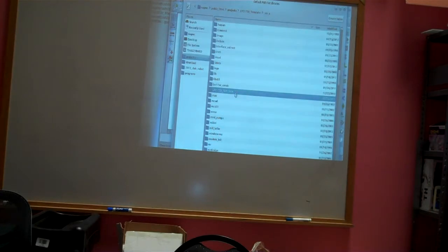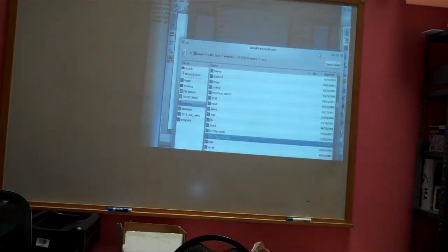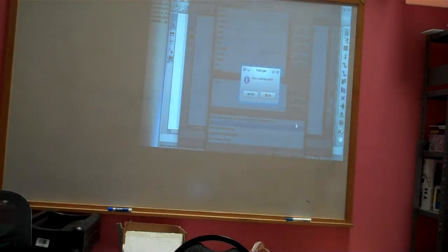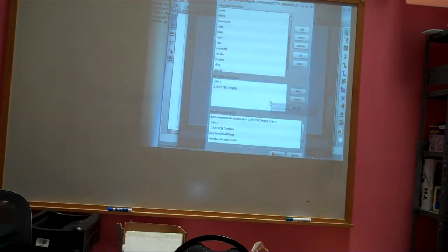So we're going to add that as a library, and because this is a really small display, we have to get everything in. We're going to click Open, and every time it asks for a relative path, say yes. Okay, it's really important to use relative paths. The reason why is because that allows you to pick up your entire project and drop it someplace else, and it can still find everything. Okay, so we've just added a relative path here.